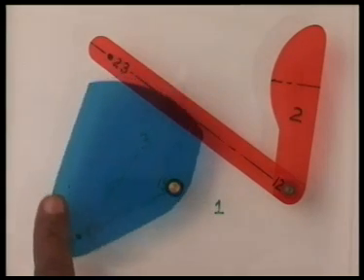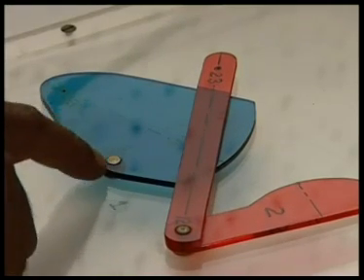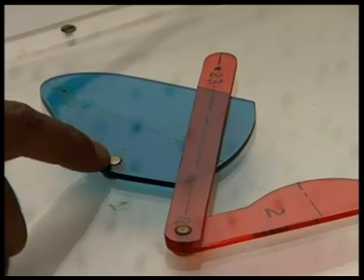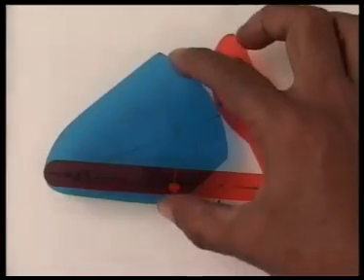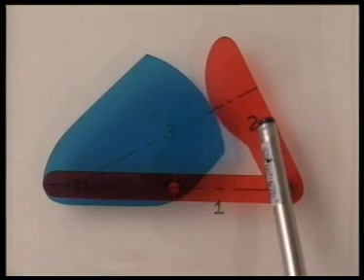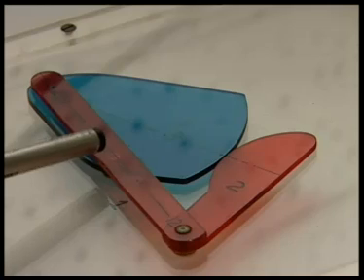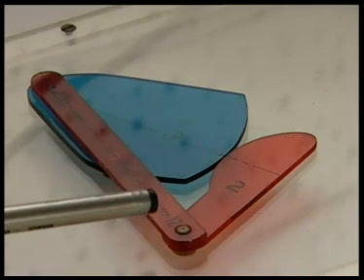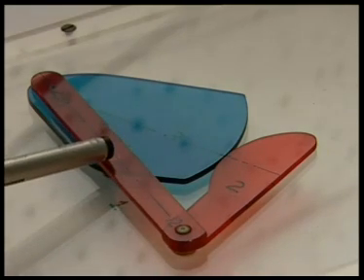Similarly, body 3, which is connected by a revolute pair with 1 at this point, I consider this as 1,3, the relative instantaneous center 1,3. Now, 3 and 2 have a higher pair at this point of contact. So, we are talking of 3 rigid bodies, namely 1, 2 and 3. 1 and 2 have a revolute pair here, 1 and 3 have a revolute pair there, which means I have located 2 relative instantaneous centers, namely 1,2 and 1,3.